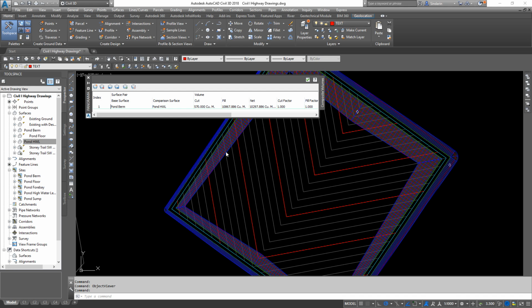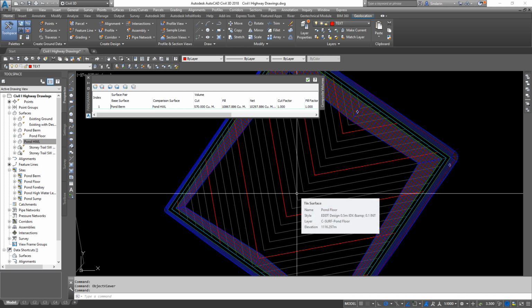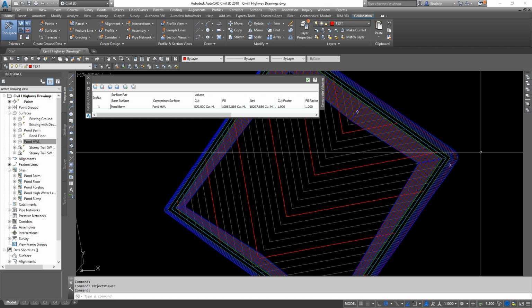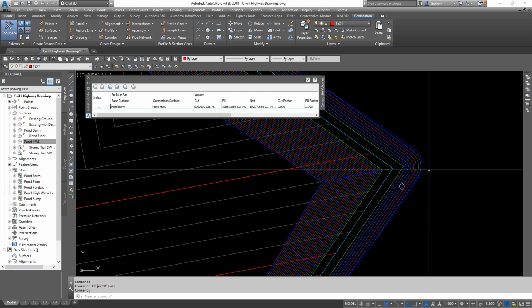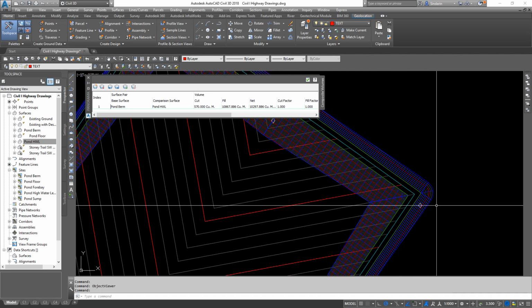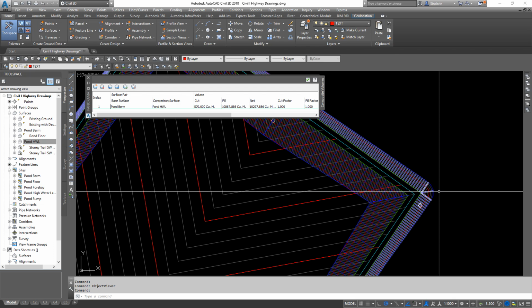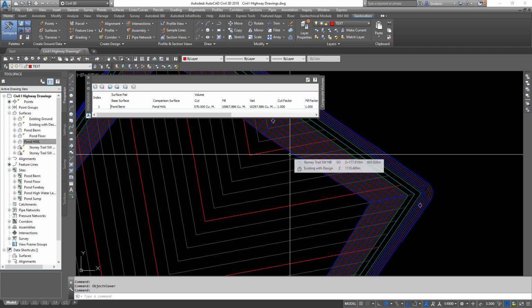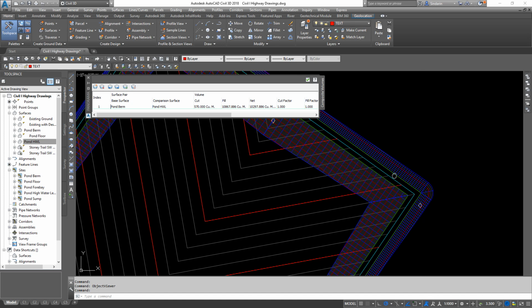Besides that, you can update this on the fly. Now, the stage storage is good if you just want to look quickly and see, okay, this elevation gives me my 10,000 cubic meters, so I can build my pond off here. Again, it's all just different various little tools to make designing a little bit easier. Now, I know I said that there's no circles, rounded parts when you're designing things. We can go ahead and make these squared off. I'll show you how to do that for the forebay, and the same steps will still apply.